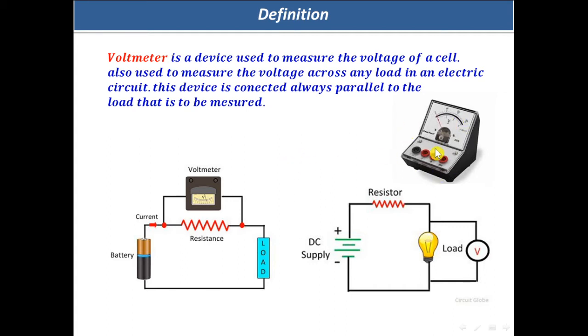You can measure with the voltmeter the voltage of a battery or also of a load such as a light. You can put it at this point and this point. I call these the corresponding ends. The voltmeter has this end, number 1, and this end, number 2. The light also has end 1 and end 2. So 1 and 1, 2 and 2, are corresponding sides.